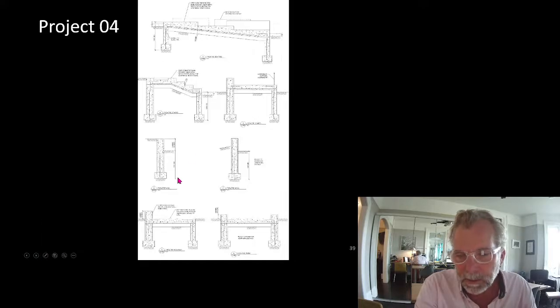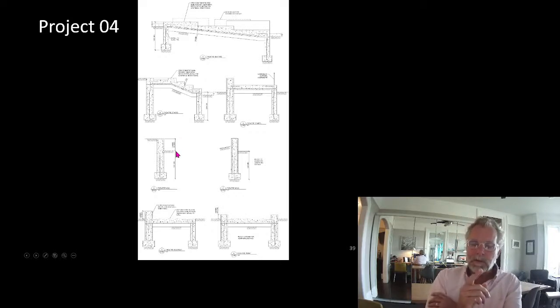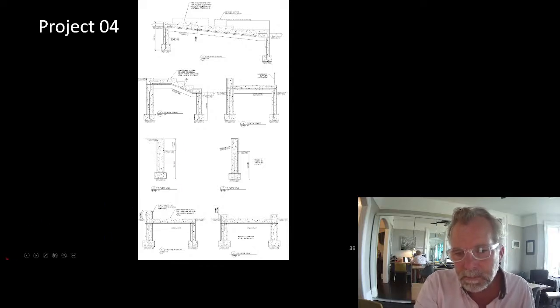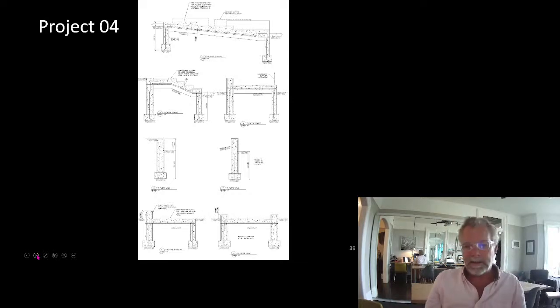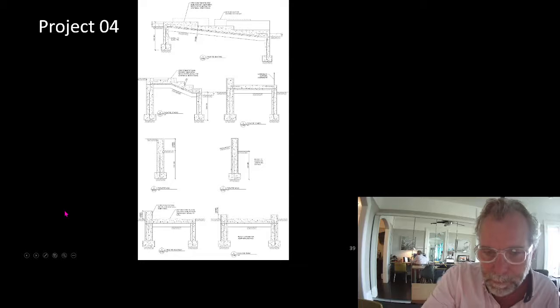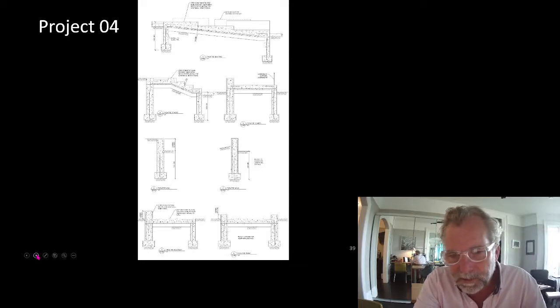So what gives? Well, we consider any wall that's retaining less than 600 millimeters of earth to be not a retaining wall, and so we put it on a nominal footing. As soon as it's retaining 601 millimeters of earth, we consider it a retaining wall, and we actually have to do the calculation. I've always meant to derive a transition formula for walls that are retaining between 600 and 1200 millimeters of earth, so we don't immediately jump from no footing at all to something wide, but I haven't done it, and it just doesn't seem to matter all that much.